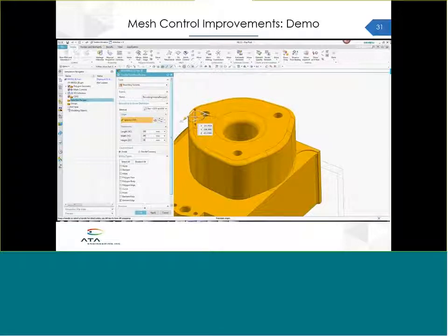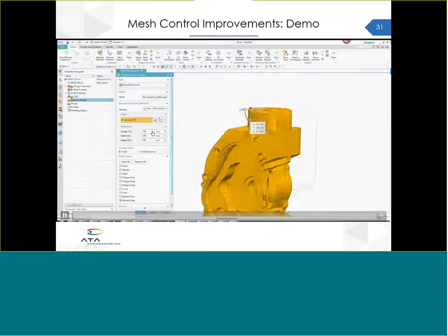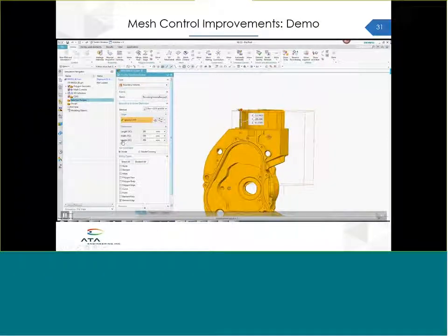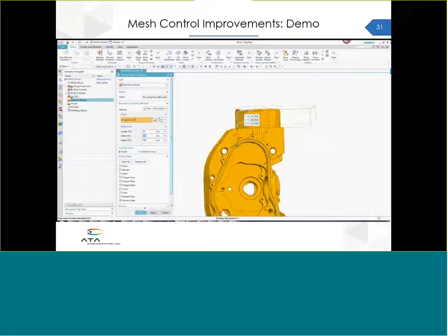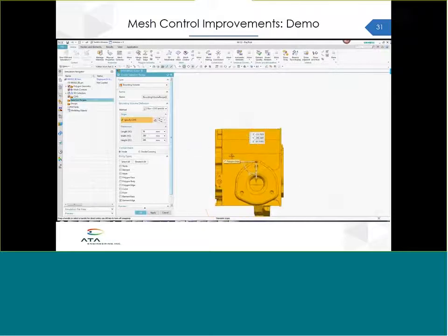You have a few different ways you can do this. You can either specify exact measurements that you made or just play with the different edge lengths. In this example, I'm just messing with the edge lengths until I get the appropriate bounding volume that I want for this region. I then have to move that bounding volume to the correct location. That's what I'm doing here. So I wanted to just cover this whole component right there.